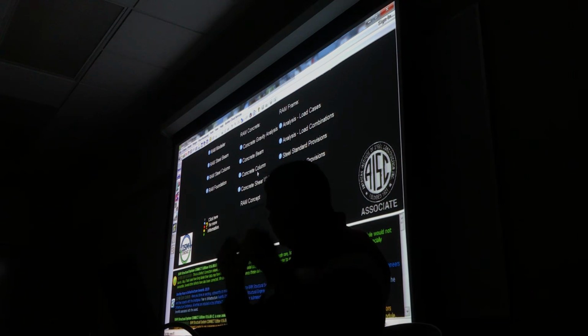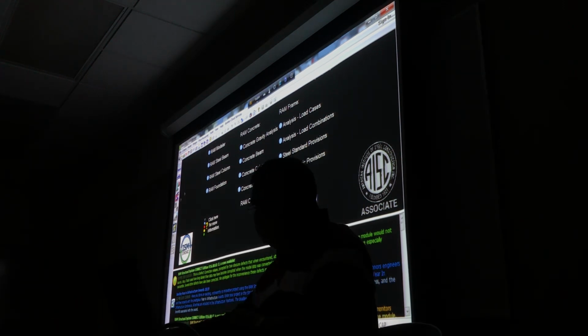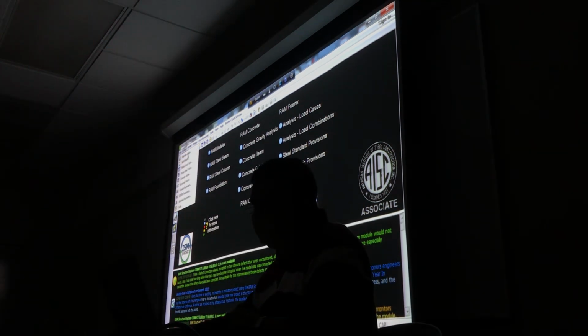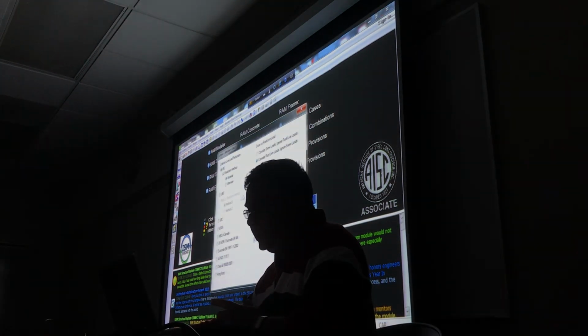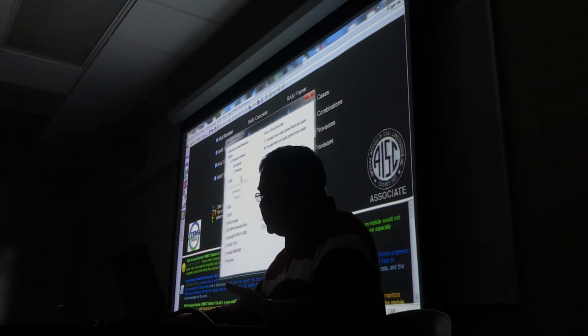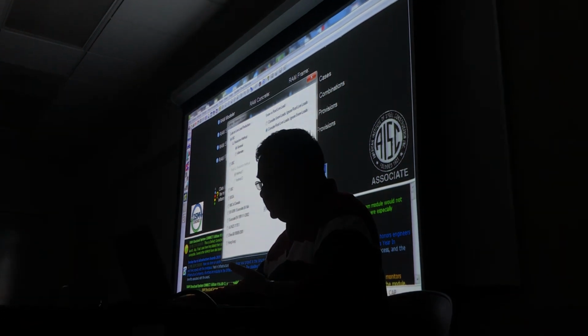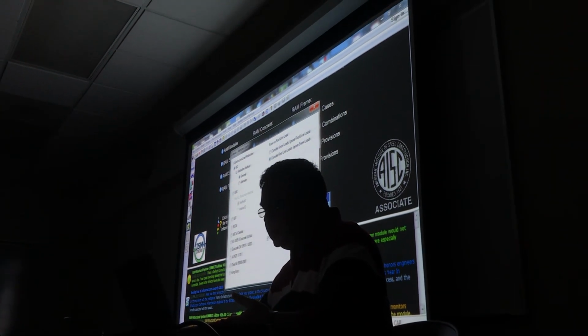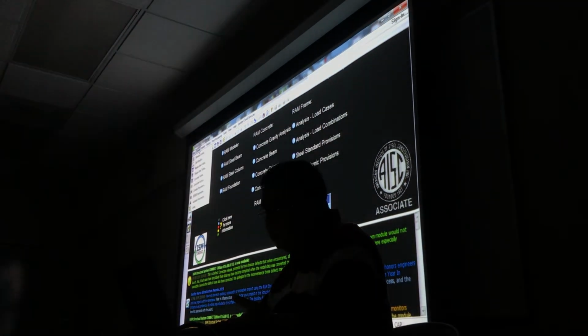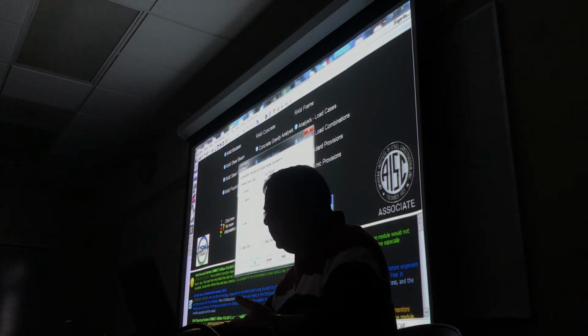Okay, so we are going to model it first. Before we model, we want to see the criteria. Okay, member loads. We are using the IBC code. IBC and CBC are the same, and there is no change anymore. So these are okay. The only thing is self weight.